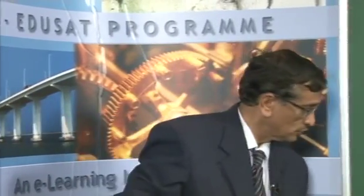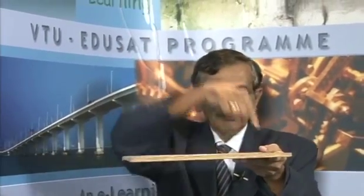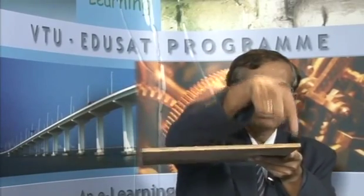So on this particular plate which is shown to you as an example, it is a horizontal plate. Everywhere the depth of water is the same. So this is gamma h, this is also gamma h, this is also gamma h. What is gamma? Specific weight of the liquid. What is h? It is the height of the liquid. So everywhere the pressure is the same. Everywhere you will see it's a hydrostatic pressure, everywhere the same.